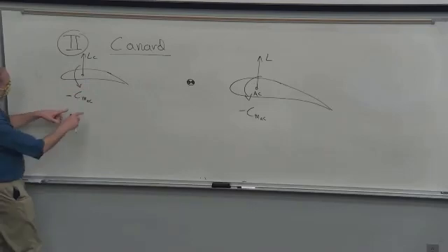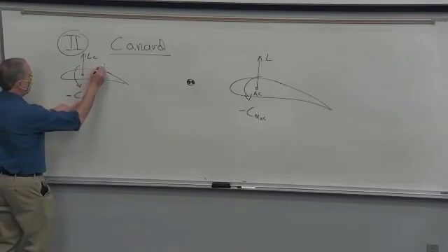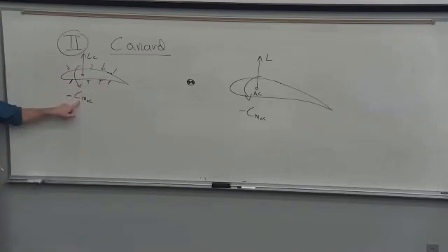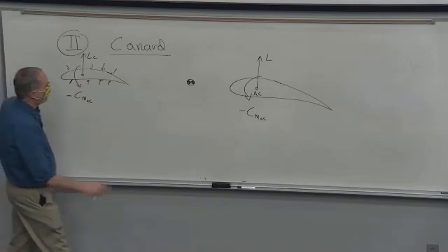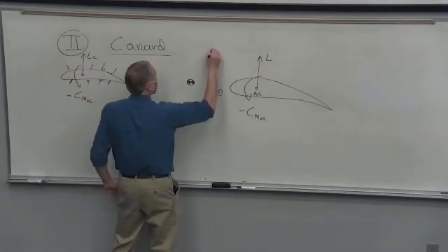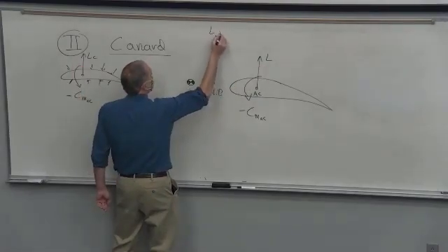Well, yeah, so this, remember, comes from the pressure distribution, the distributed load, where you get a pure couple, and then you get the net force as well. And that's the stuff you do in statics with the distributed loads. And so the secret here is to choose the CG so that the net resultant of this lift and this lift acts behind the CG.